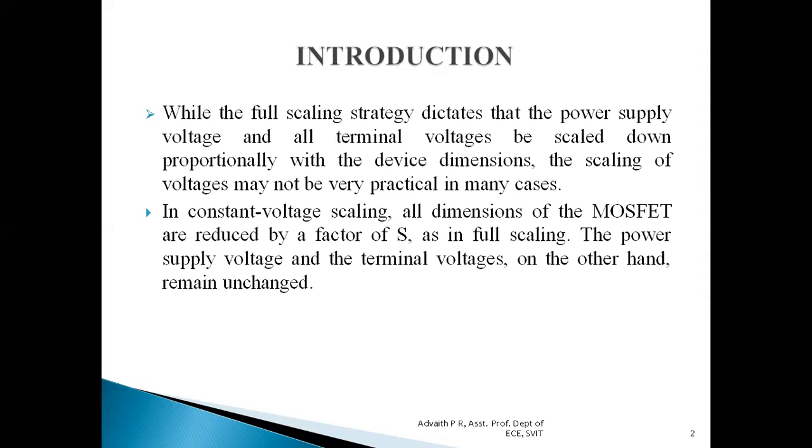In this particular scaling called constant voltage scaling, all the dimensions of MOSFETs are reduced by a factor called S, as in full scaling. The power supply voltage and the terminal voltages, on the other hand, will be untouched or will remain unchanged.